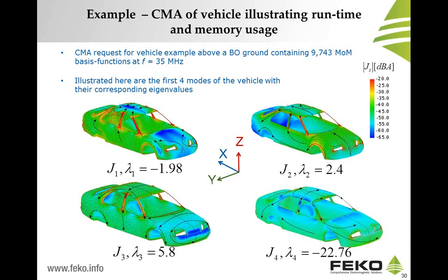Now, for simpler structures, such as the MIMO antenna considered in the previous example, the number of unknowns may be quite limited, or it may be less, and our eigenvalue solver can get answers quite quickly. But as the number of basis functions becomes quite large, so does our computational complexity, or the time and memory required to obtain a characteristic mode solution becomes more and more.